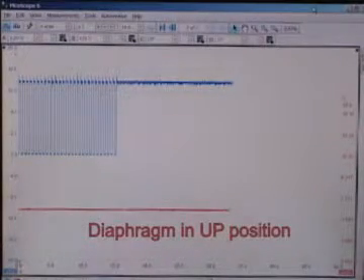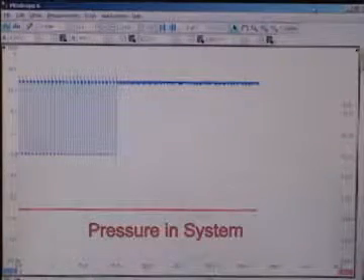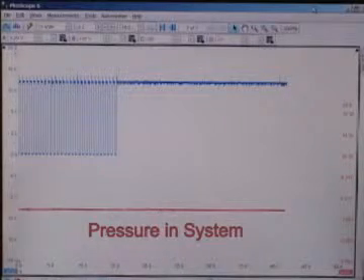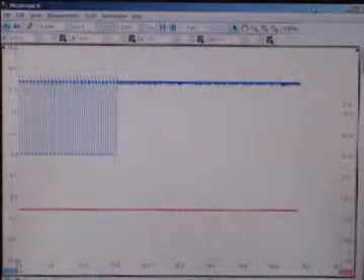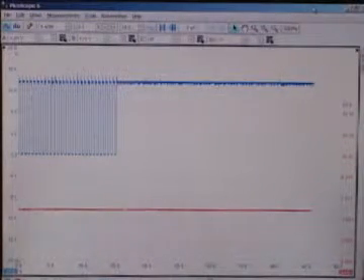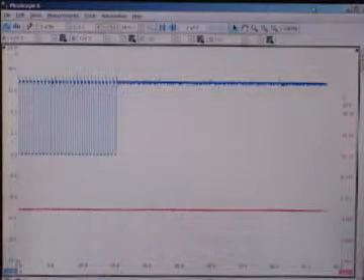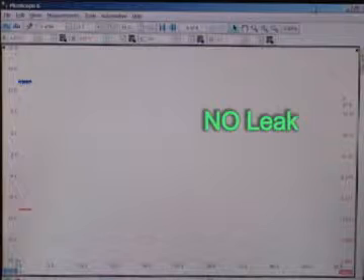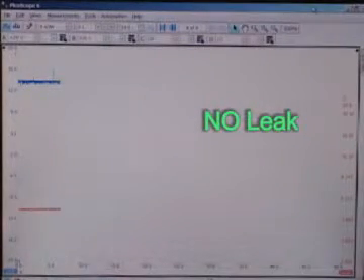When there are no leaks, the diaphragm will be suspended due to the air pressure created by its movement, and the waveform on channel B will stay steady at 0 volts during the LDP solenoid rest time, which is the pump period. A change in the signal during the solenoid rest time or during the pump period indicates movement of the diaphragm and a leak to be present. The PCM verifies movement of this diaphragm by monitoring the LDP switch circuit transitions.